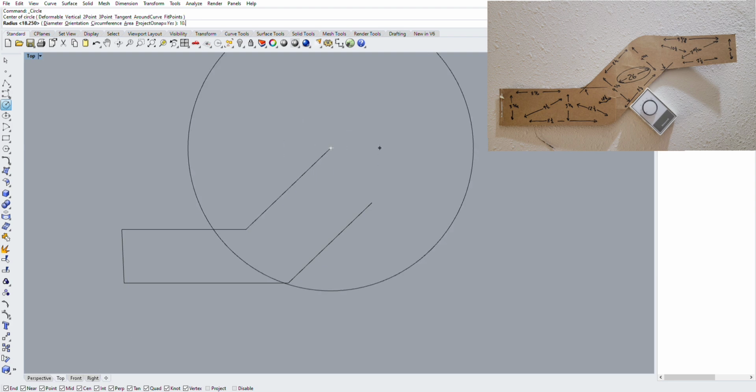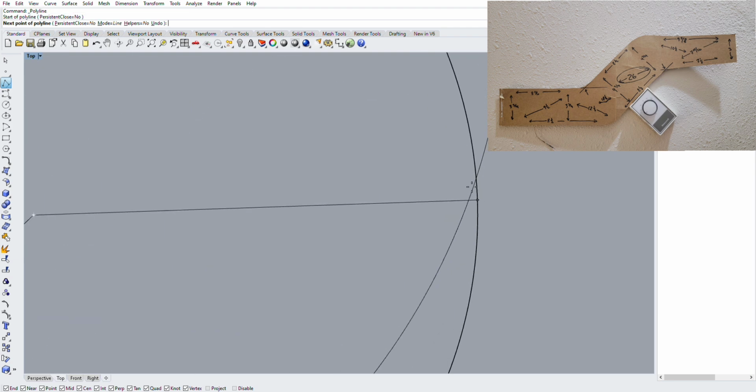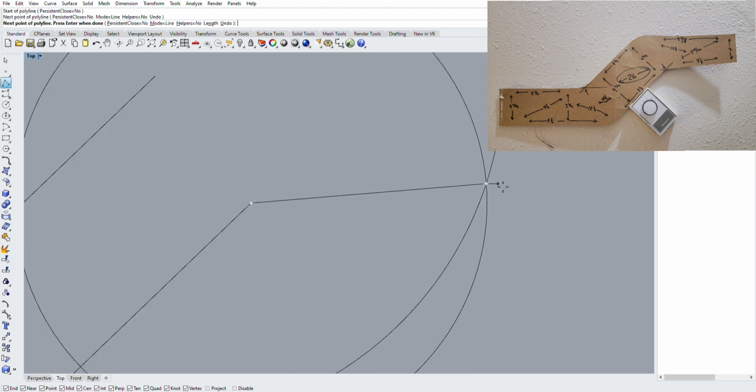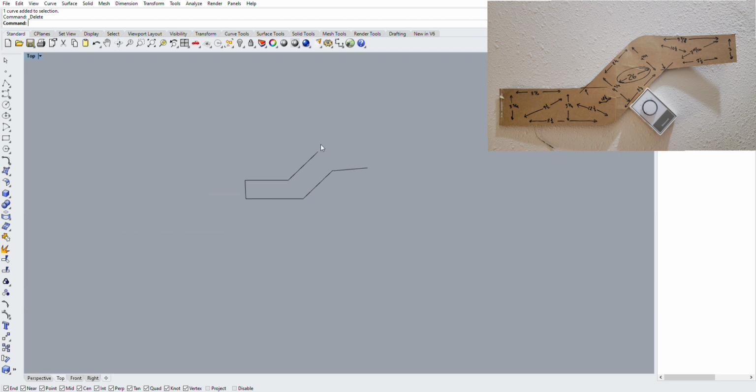It happens so fast. But again, from that very top point, you can use the measurement across the top, use our radius command, use our radius from the lower one here, and this is giving us our line across the bottom. We're just going to keep repeating this. Now, we're not measuring angles here. We don't have to look at angles. We're not even using them.